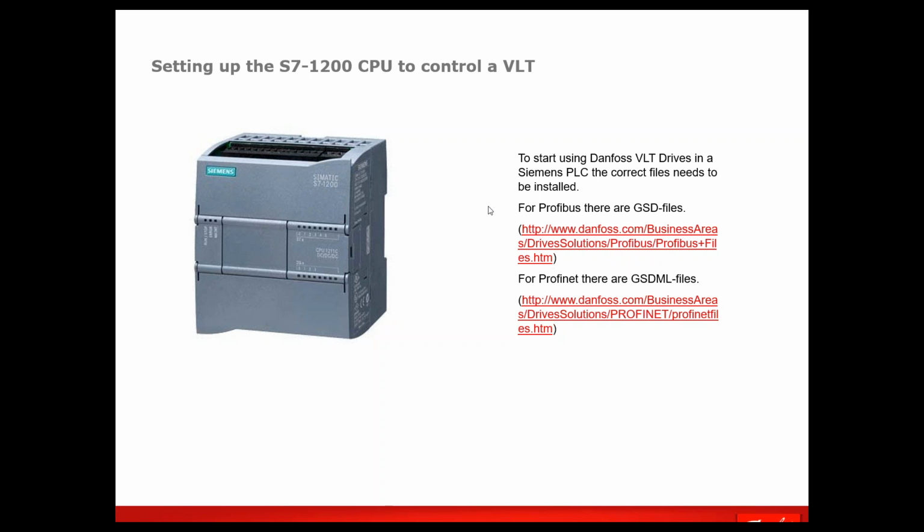We do have, on danfossdrives.com, starting there, these addresses may not be correct anymore, I'd have to look them up, but we do have the GSD files for the Profibus options through the downloads section, as well as there's Profinet. The setups between Profibus and Profinet are the same. Even the function blocks are the same. The only thing different is the identifying file that you would use.